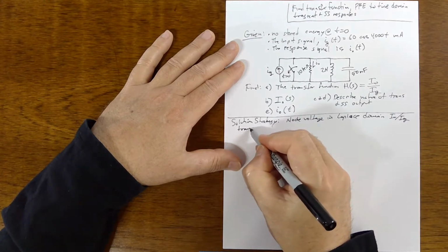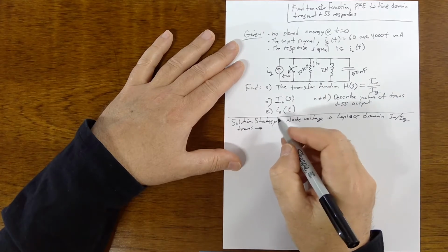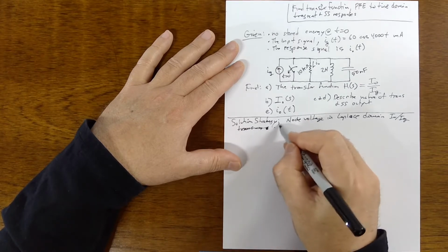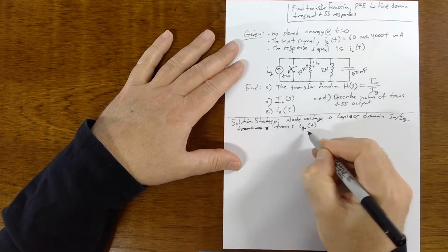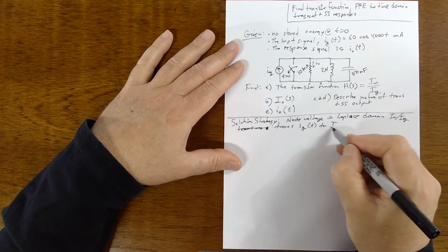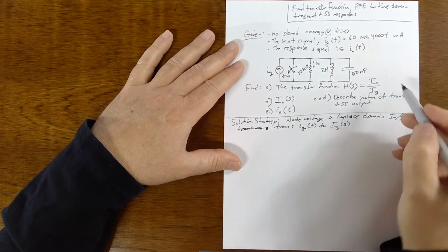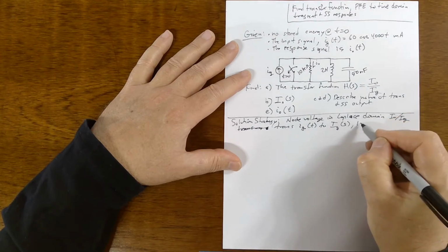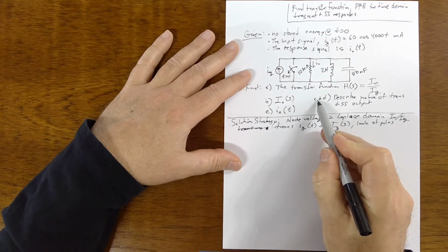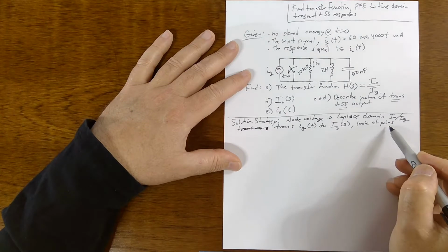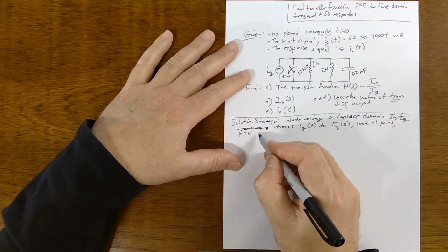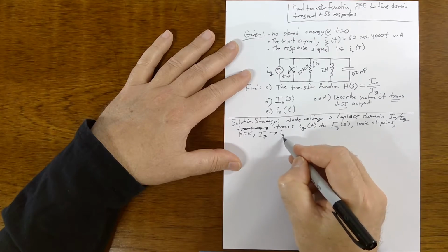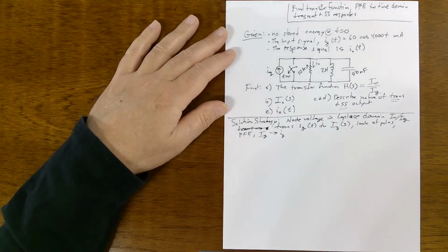Then we're gonna transform to S domain. Wait, no, sorry, we're gonna transform I_G of t to I_G of s. We're going to transform from the input signal, this thing, to the Laplace domain, and we're gonna look at the poles, and that gives us some input into the transient and the SS response. Then we're gonna do a PFE, and we're gonna take I_G back to little i of t. We're going to go from frequency domain back to time domain. That's what we're going to do.